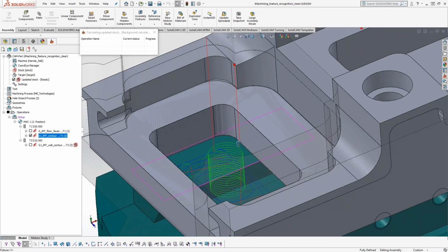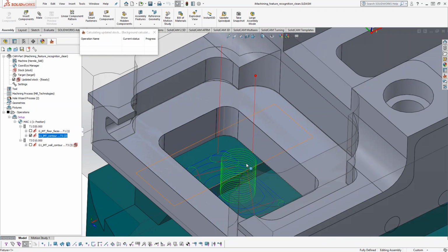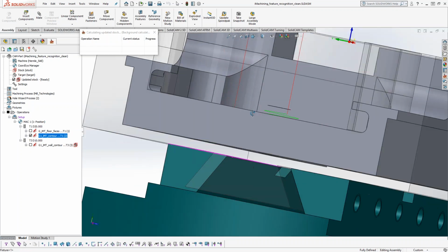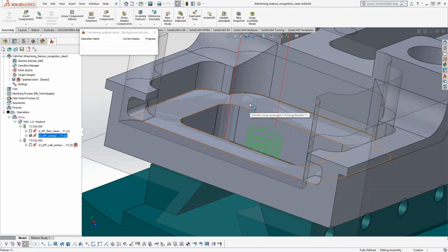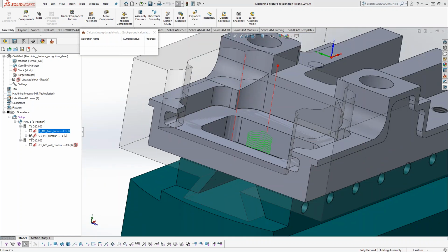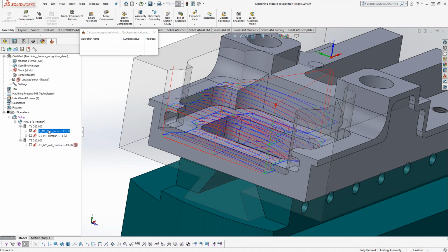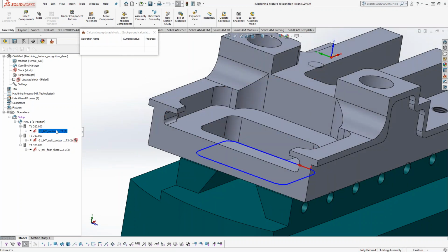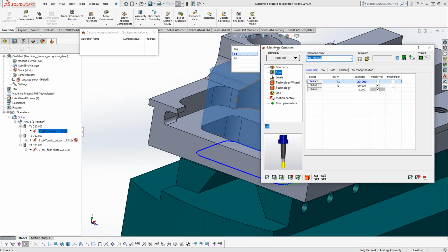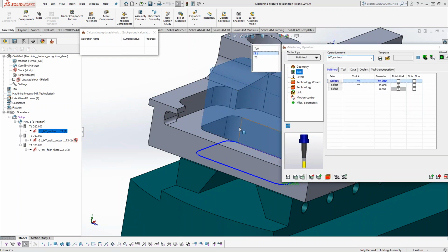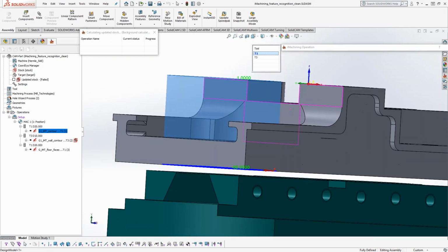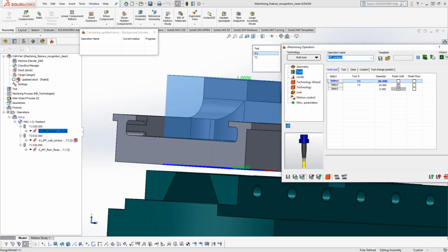No, it's cool. So we can see that it started from this top face because we already machined it. What if we didn't machine that face? What if this first operation here, we took this and dragged it down to the bottom? Now, when we open up this through pocket, what do we see with the preview? We now see the preview automatically changes the upper level to the highest point of the stock. So, and if we drag my, let's see, what do we want to do here?